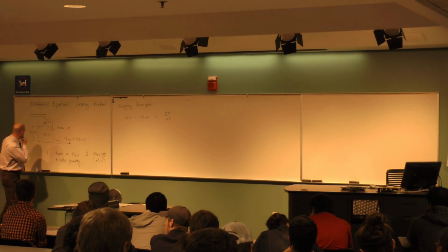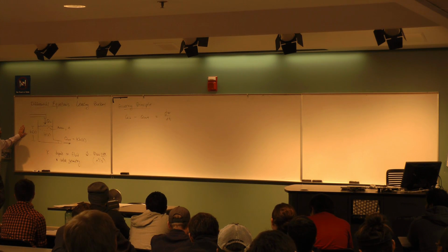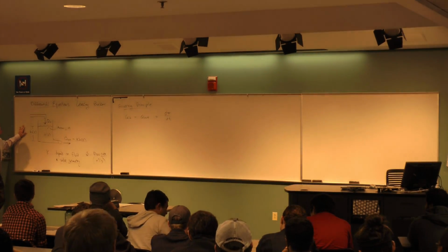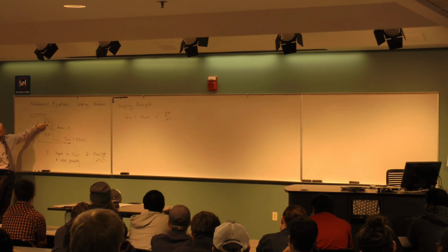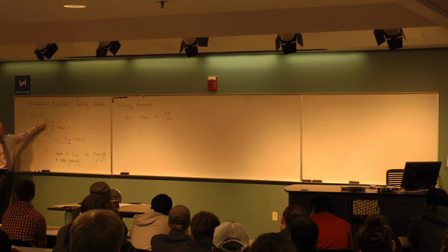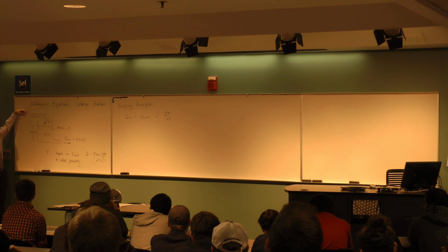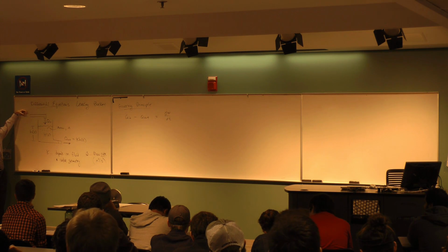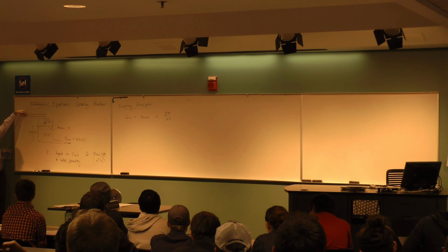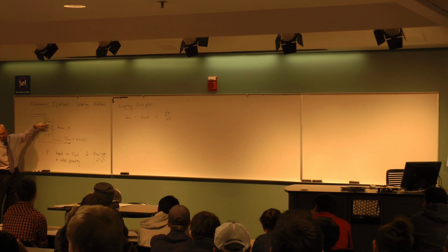So can we get an equation for the height as a function of time? Let me ask you this. Does Q in depend on the height? This is what I control. This can be anything. I could be over here with the knob. I've done this on the final exam, by the way. I could move the knob back and forth in a sinusoidal fashion, so I could have a sinusoidal Q in, no problem.